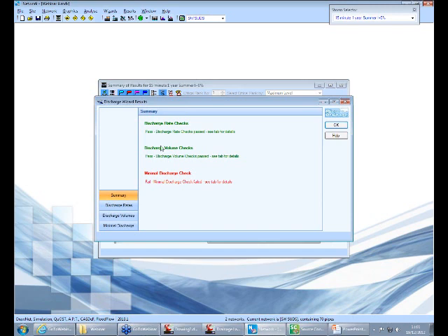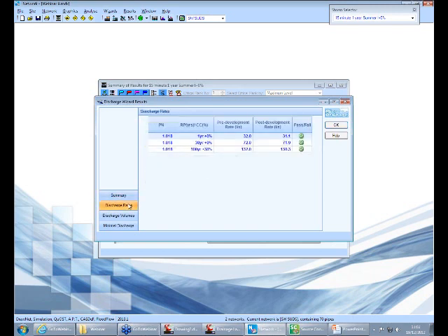So looking at the tabs on the left-hand side, already we can see there's a difference in color between the different tests. So green meaning that we've passed. If I click on the discharge rate tab, you can see that the pre-development rates are higher than the post-development rates. So great job there, James. Well done. Managed to hit all 3 with the 1, 30 and 100 year.